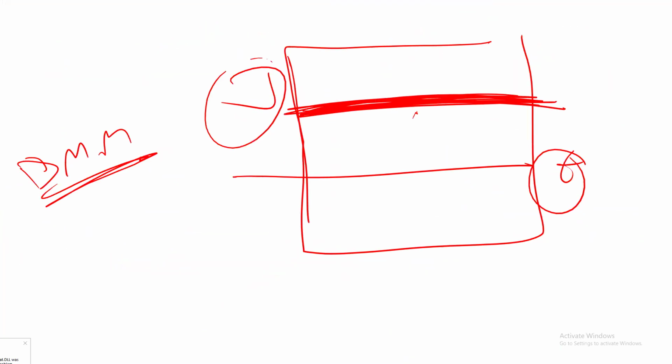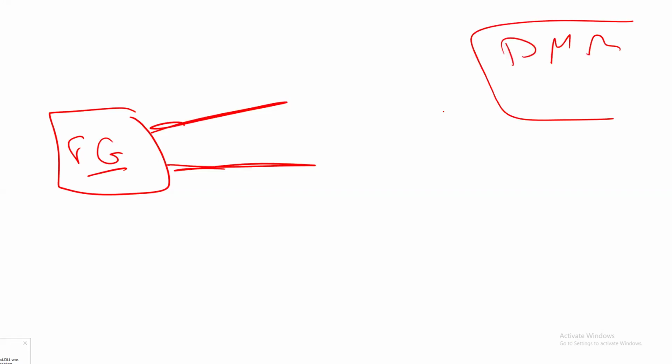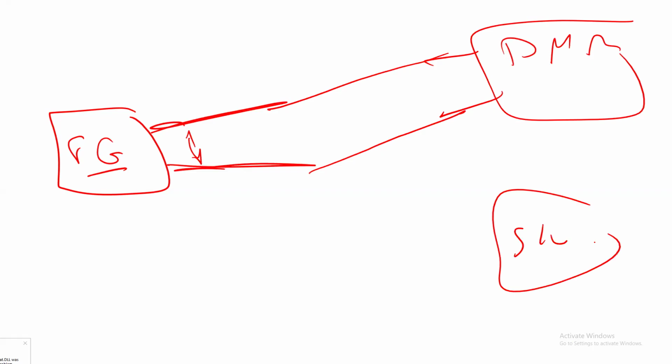If this is the function generator, the FG, it has 2 outputs this way. This is the DMM used before. Also, it has 2 outputs. So I'm going to connect them together here because I want to measure the output signal. Same thing for the oscilloscope. Also, I'm going to connect them in parallel this way. Okay.